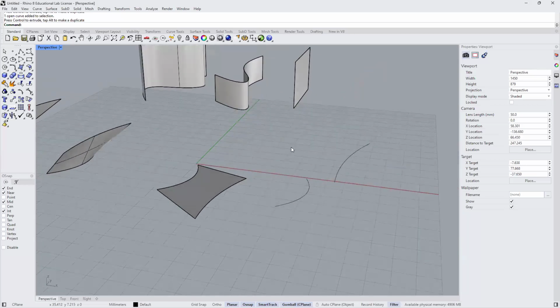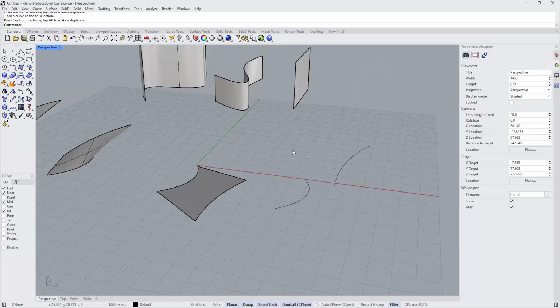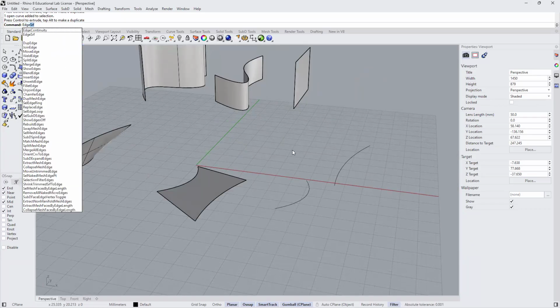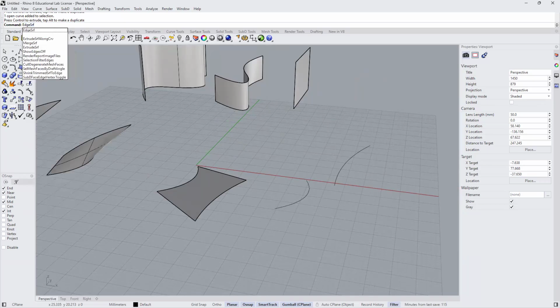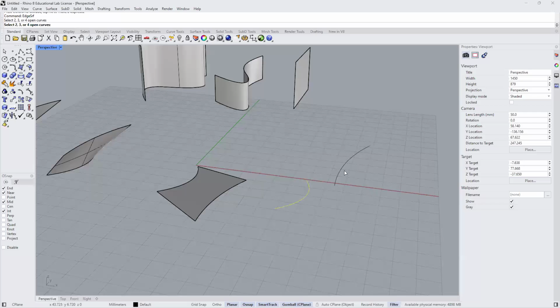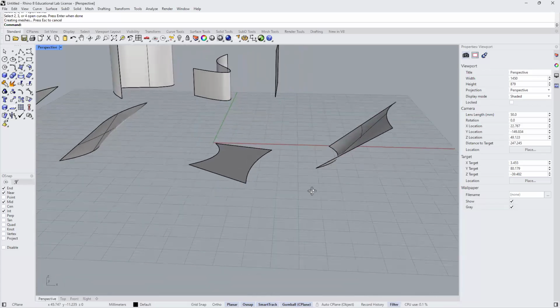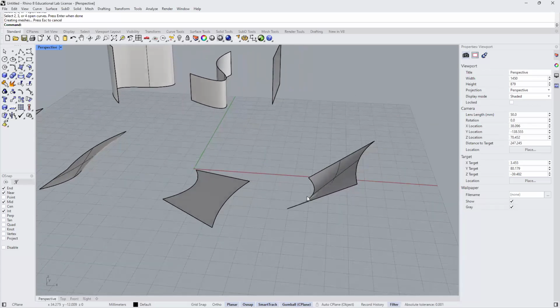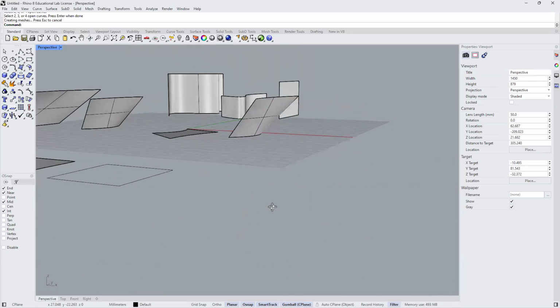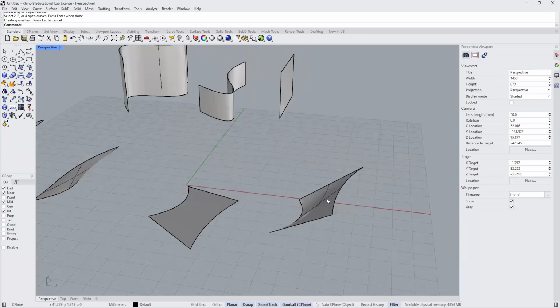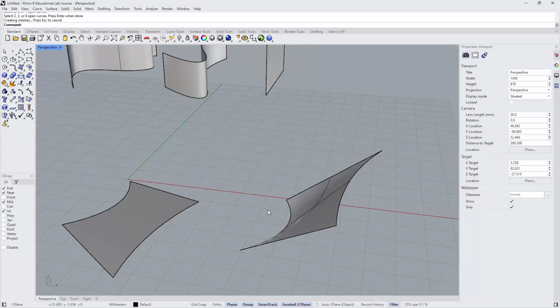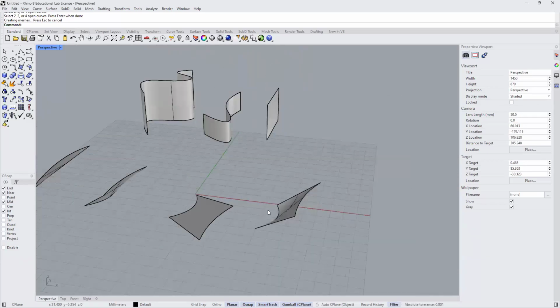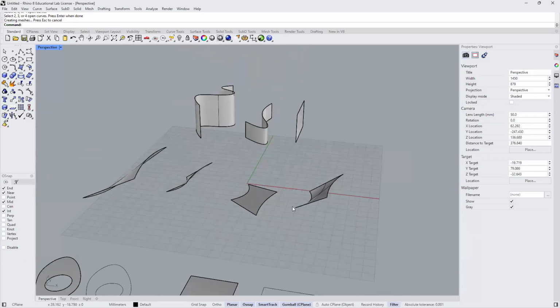And now what I'd like to do is repeat that same command, which is the edge surf. So EDGE and then SRF, edge surf, enter. Select my curves, 1 and 2, and enter. So it generates that surface. And it's almost like a sheet. It's very flexible, which is really nice. And I could have done that with 2 lines as well, but I decided it was better to try 2 curves and get some complex shape. So that's that command, the edge surf.